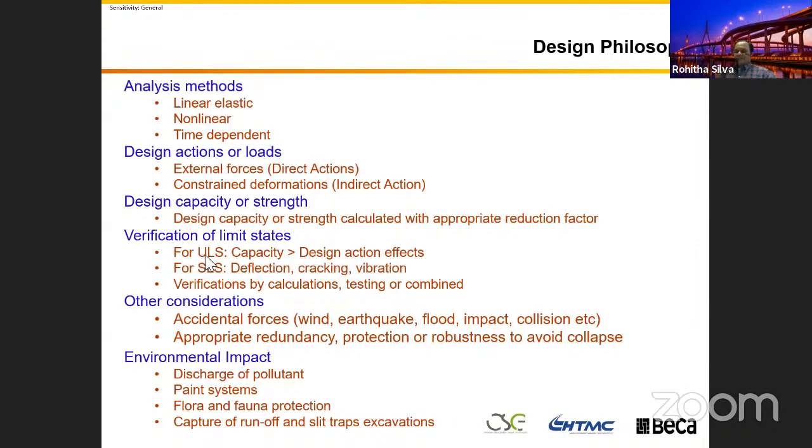Of course, when you design, your ULS capacity has to be bigger than any design actions due to the design effects. Because when you put the traffic load on the bridge, and your dead load and superimposed dead load, wind load, earthquake, all sorts of load, when you combine them together, whatever action you calculated, you have to make sure your design strength is higher.